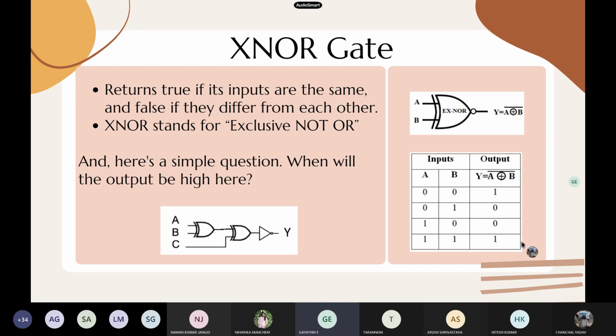So if it is the negation of that, what is the pattern the input combinations follow here? You're right if you guessed it to be having an even number of 1 bits in them.